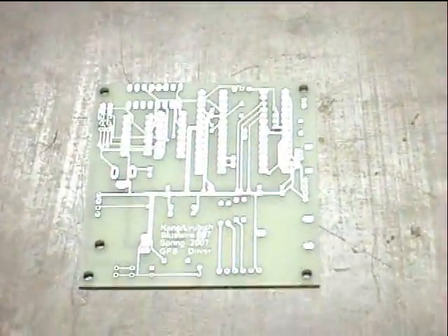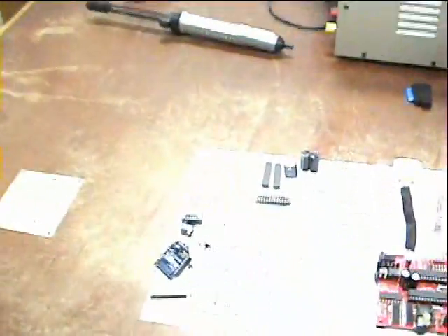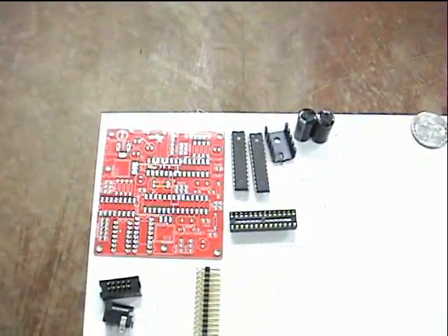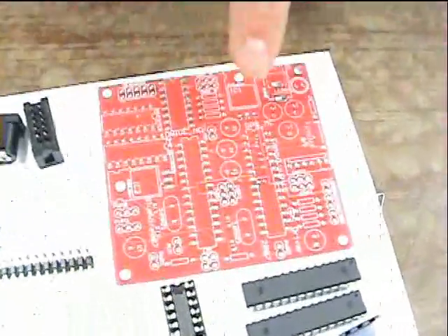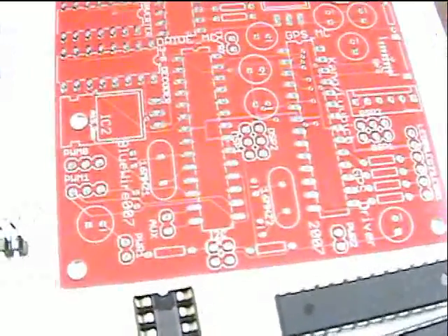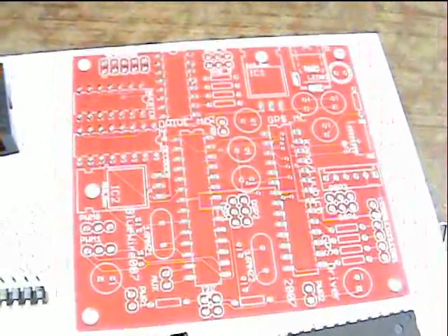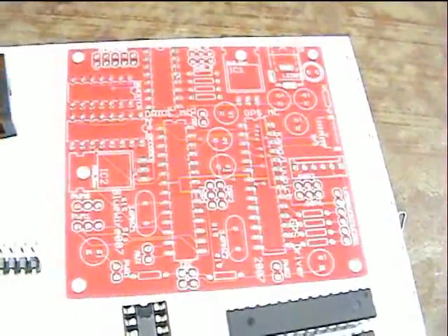Then when we tested it out and made some changes to it, we redid some of the parts on the board and came up with the design on the right, which is a much smaller version of the first prototype. This one does have the silk screening and solder mask. As you can see, all the components are labeled and all the wires are covered. Therefore, no interference or scratching can occur. And this is the red solder mask, so that's why the board is red.